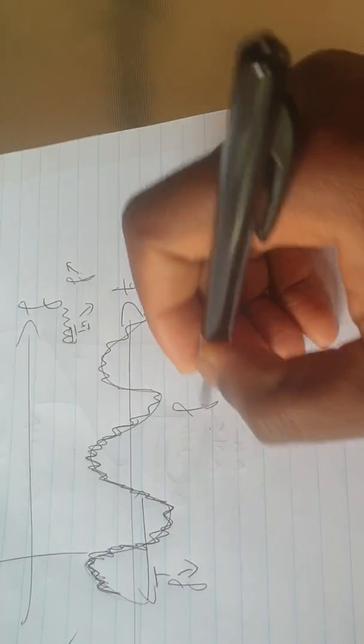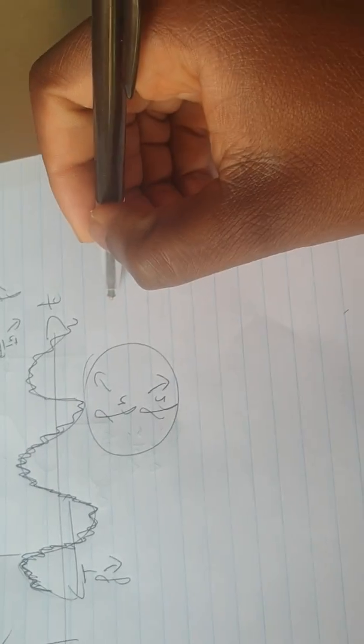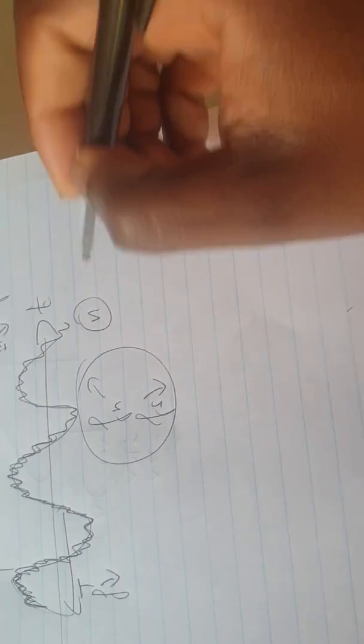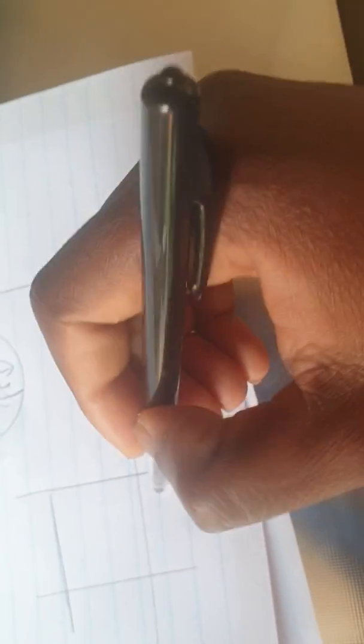Noise is at a high frequency compared to the actual signal, which is at a lower frequency. You just have to design an electronic circuit that we call a filter that will cut out or filter out the noise. So for it to filter out the noise, it only has to pass certain frequencies below a certain frequency threshold that we call the cutoff frequency, and attenuate.